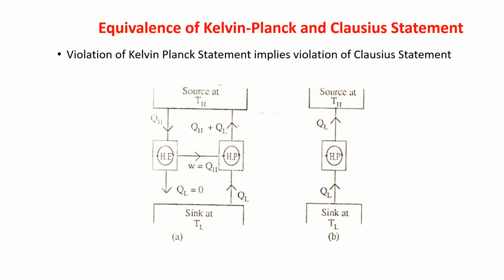The other way. Let me consider another case. Let us say this heat engine is taking heat QH from the source at TH, and it is not rejecting any heat to a low temperature reservoir, converting all heat into work. So W is equal to QH. I will give W to this heat pump so that it will take the heat QL from the low temperature reservoir.